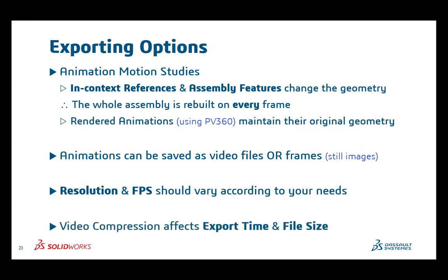Okay, the last thing I want to talk about is video compression. I know we're getting really close on time, so I'm just going to end with this. Video compression is when you want to minimize the size of the end result of the video that you export from SolidWorks. Let's say you've got a 10-second animation. You don't want to end up with 1 gigabyte of video files. You want it to be as small as possible, right? Because it's just 10 seconds of video. Video compression affects two things: the file size, which is the end result, but also the exporting time, because there's an algorithm working in the background to compress all of that for you.